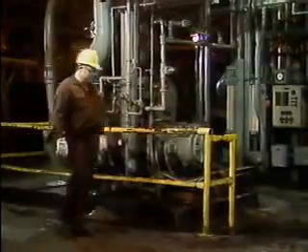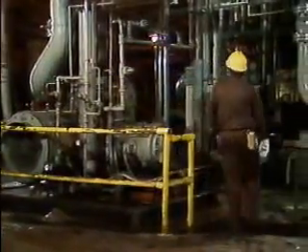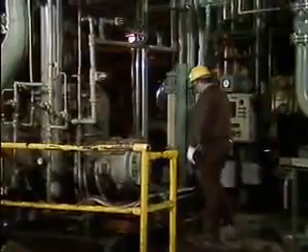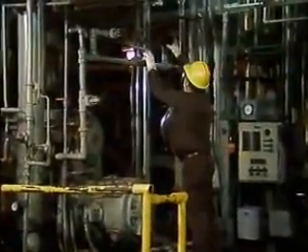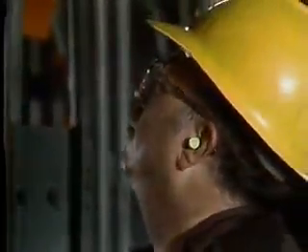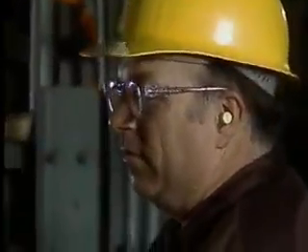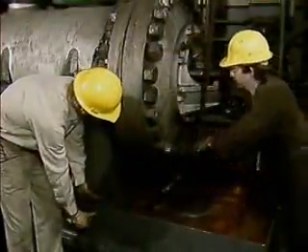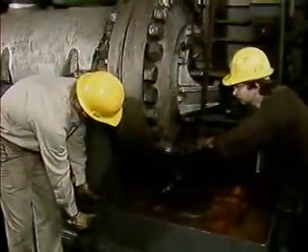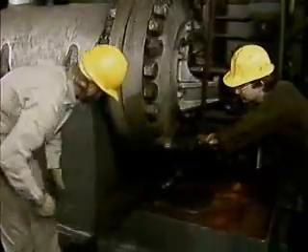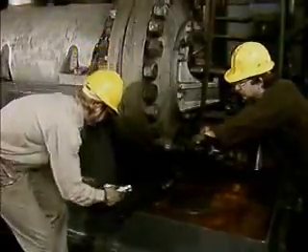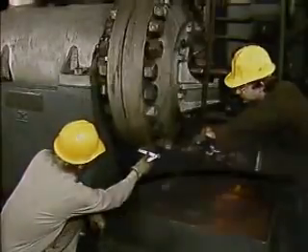There are also hazards associated with compressed gas systems. For example, leaks in a compressed gas system can blow dirt or dust around the work area at high speeds. For this reason, eye protection, such as safety goggles or glasses, should be worn by personnel working around these systems. Pneumatic tools and rubber hoses that are used with compressed air systems must be kept in good condition and inspected before each use. If the equipment is not in good condition, an accident could happen. If a 120 psi air hose parts, it could whip about and strike someone nearby, causing a serious injury.